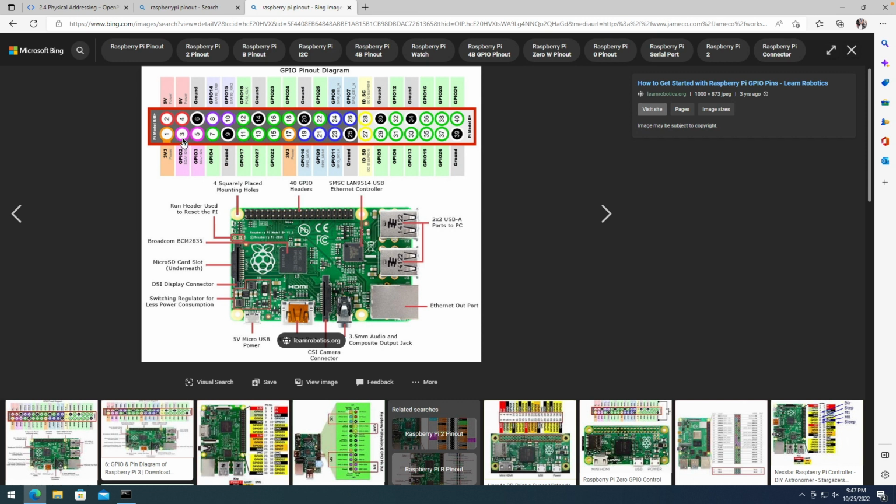So they are always reading true, okay? So the buttons you're going to wire to those two pins are actually going to close to ground. So just keep that in mind. That's only true for those two first pins. All the other pins don't have anything connected to them.